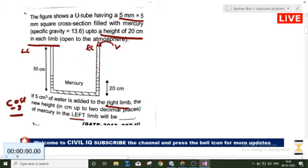Due to this, the mercury level in the right limb will try to fall, and there will be some gain in mercury level at the left limb. As mercury is an incompressible fluid, whatever the fall in mercury in the right limb, the same amount of mercury will be gained in the left limb.